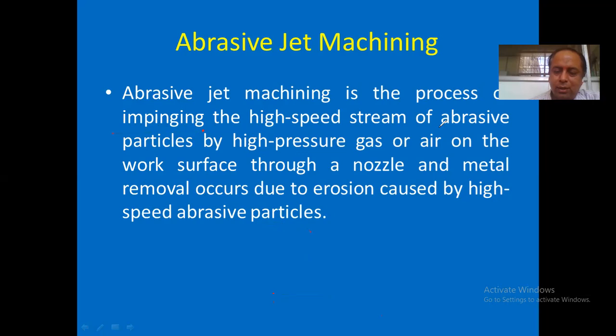So actually the particles cannot move by themselves, so we use a high pressure gas, normally air. Depending on the case, we can also use helium or an inert gas. But generally air is cheap, and there is not much of the problem that happens in welding, where gases react, because no temperature is involved in this process. We are doing the machining because of mechanical action, so we do not have much problem if we use normal air.